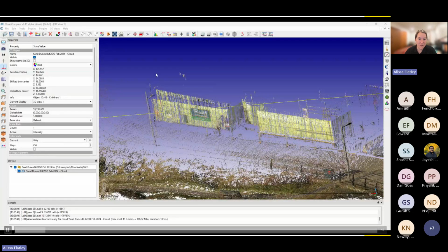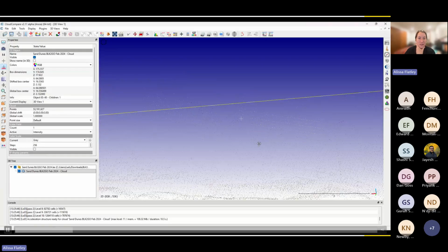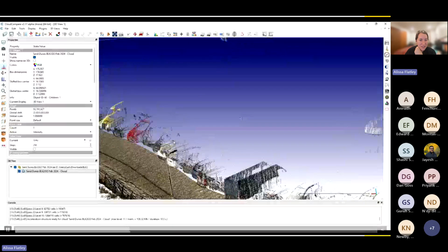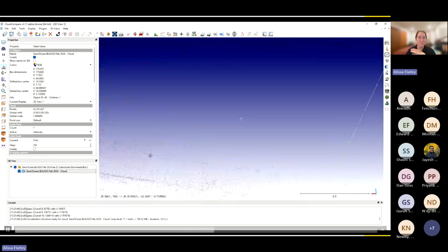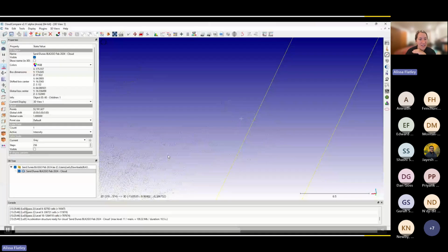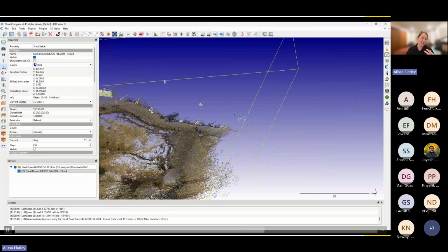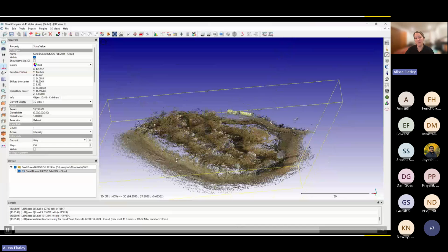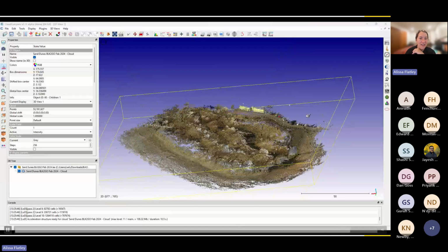So you've completed the survey, and it looks good until you zoom in and you start to see, sorry for the flickering, some weird things happening, like cars being parked too close together in an unnatural state, some building misalignment, which essentially means that there's a lot more noise in the point cloud compared to what you would want from a cleaner point cloud. At that point, I found it quite hard to trust the rest of the point cloud, given that there were some interpolation issues.